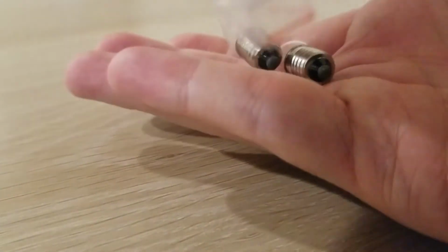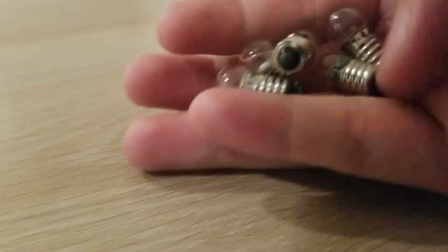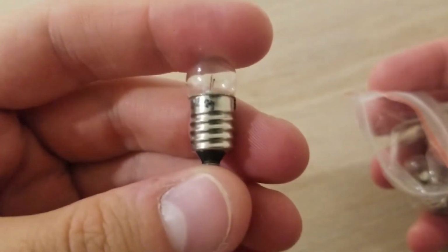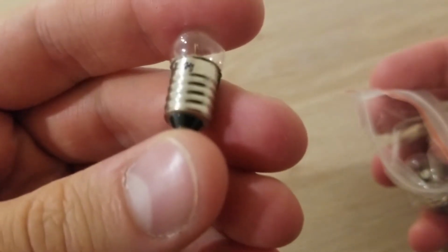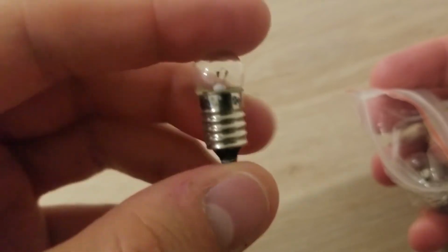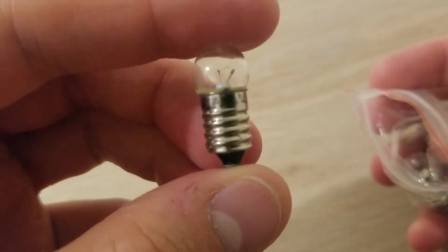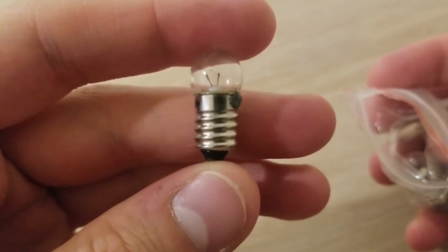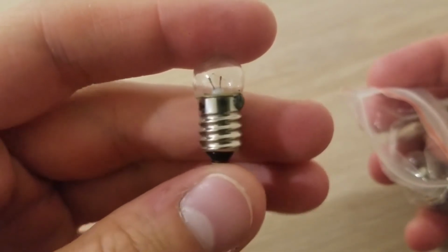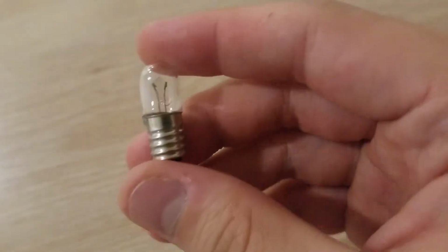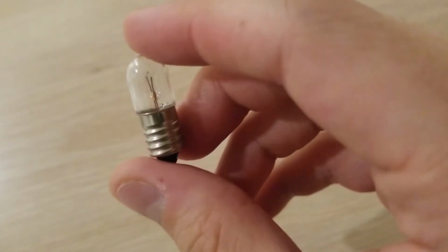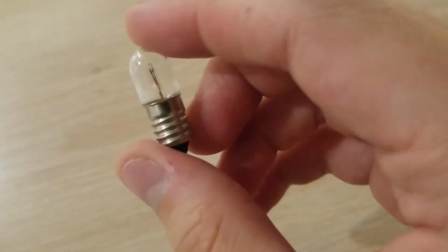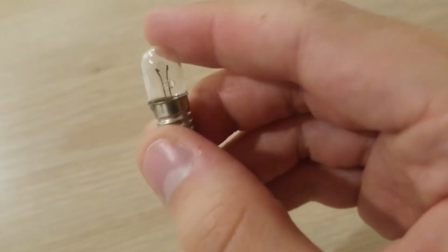Your board also comes with 5 mini lamp bulbs. These bulbs are rated at 2.5 volts and come with an E10 style base. While even proper use will eventually wear out the filaments in your bulbs, the nature of this experiment puts extra strain on them by switching them on and off repeatedly and by sometimes supplying more voltage to them than they are designed for. When this happens, don't worry. Just look for 2.5 volt bulbs on an E10 base. My replacement bulbs were rated for 1.25 watts of power and they worked great.